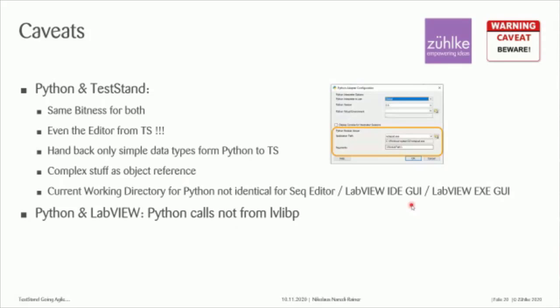And as a goodie, one of the things that I didn't know, and which is not so much propagated: in packed project libraries, the runtime engine equals true evaluates always as false, no matter if it's actually true or false. So this was one of the goodies that I didn't know of. So perhaps you avoid this mistake that cost a little bit of time from my side.